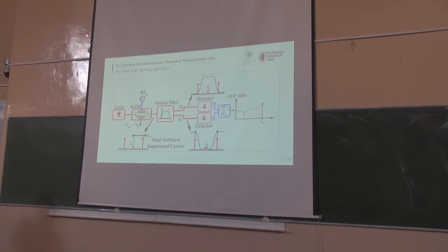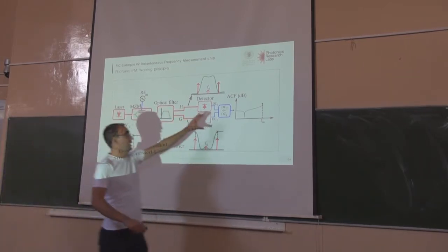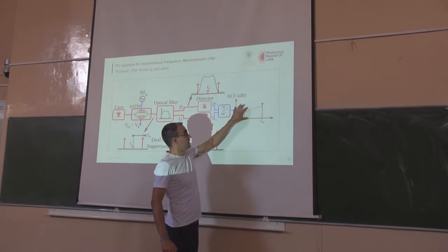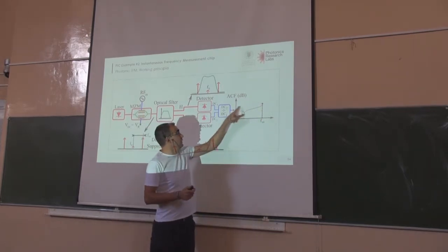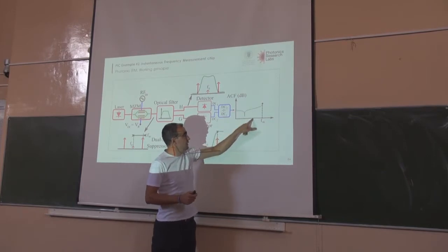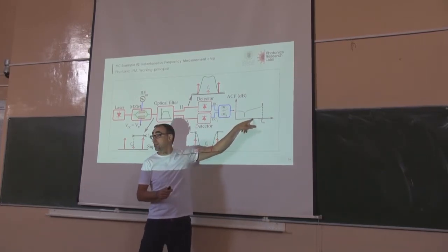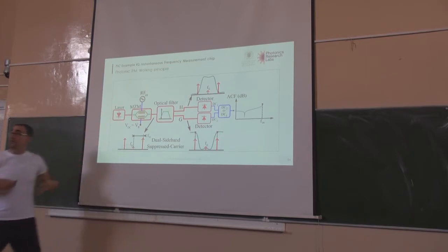And you did it by photonic means. Okay? That means that if you calibrate your system and have this function stored maybe in your processor, and you get this amplitude, then you immediately can tell which RF frequency you are receiving. Okay?